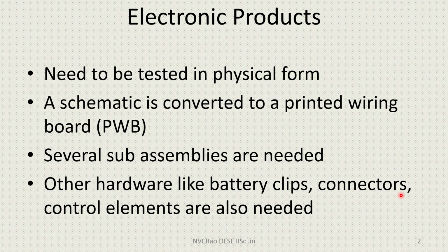Now we have several decisions to be taken saying, does this connector go on the external case or does it go as part of the printed wiring board? So even today both options are available. You can mount them on the printed wiring board or alternately put them in the case. That is where to take a decision you just need to put everything together at least the first time.